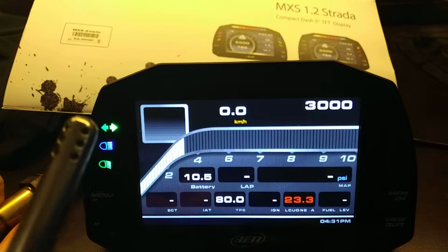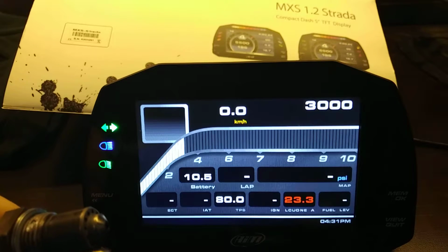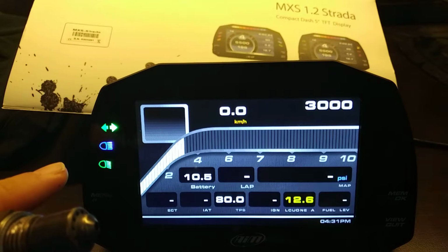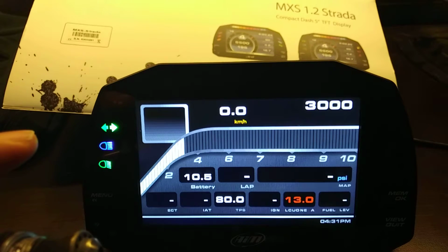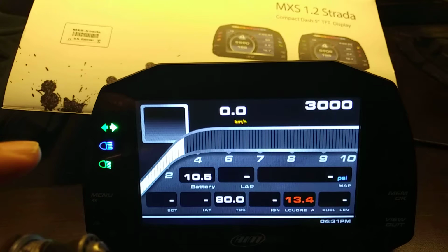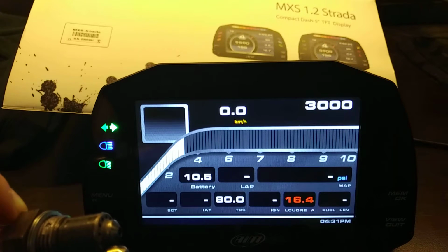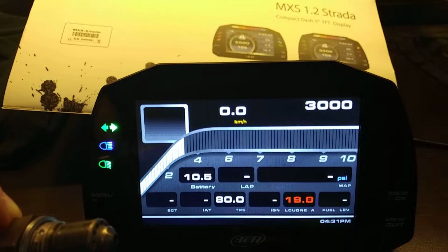So if I just take a simple barbecue lighter and inject some butane towards the sensor, you'll see it will get richer. So we can go towards stoichiometric, and then when we hover around 12.5, you can see the warning starts to go away around 12, and if we go quite rich under load here, if I inject some more butane, the warning will go away.